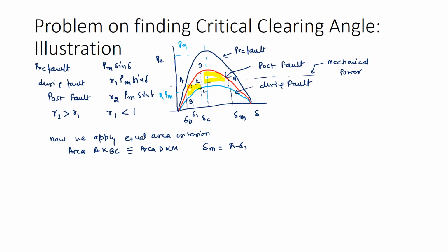But from A to D to M, these are all the operating points where the electrical power and mechanical power can be compensated. So, beyond this point, no value of delta is capable of bringing the electrical power equal to the mechanical power.